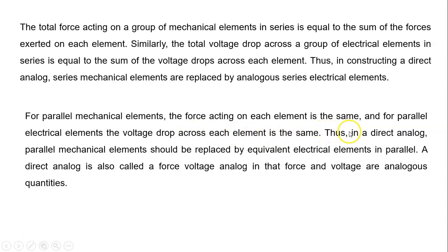Thus, in a direct analog, parallel mechanical elements should be replaced by equivalent electrical elements in parallel. A direct analog is also called a force voltage analog, in that force and voltage are analogous quantities.